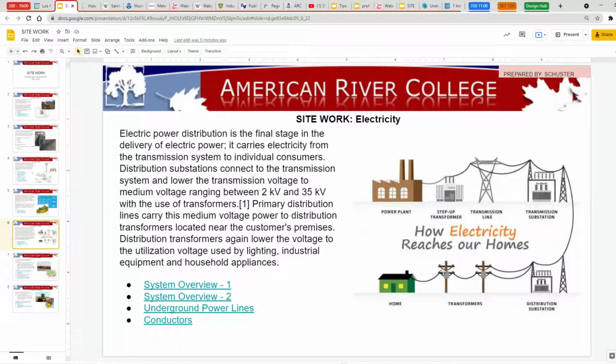And in each transformation, you lose usually 5 to 15% of the energy. And so if you've got solar panels and you transform it to alternating current to get onto the grid, and then you transform it back, you're getting about 60 to 80% of the energy that is developed on those solar panels.